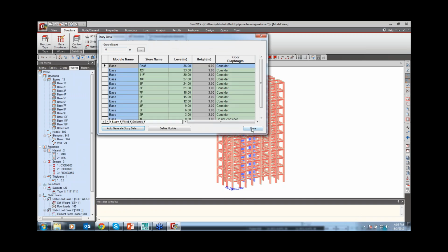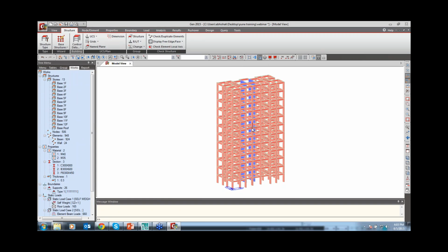Okay, these things. And one more question, that for the column size changes, you have to particularly select one property, one member, and from the tree menu you have to generate the property and you have to just drag it to the screen. According to the UI drive, that particular property is assigned to that member. So for each and every layer, you first select the element and then drag it to the screen.